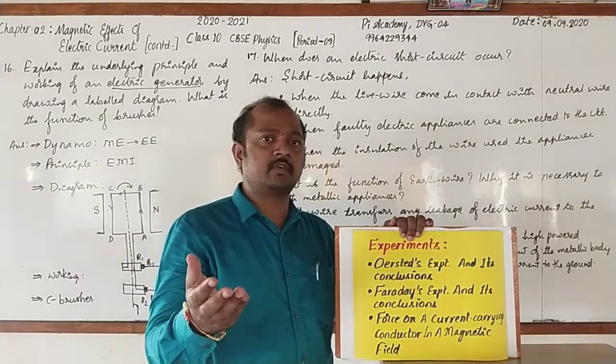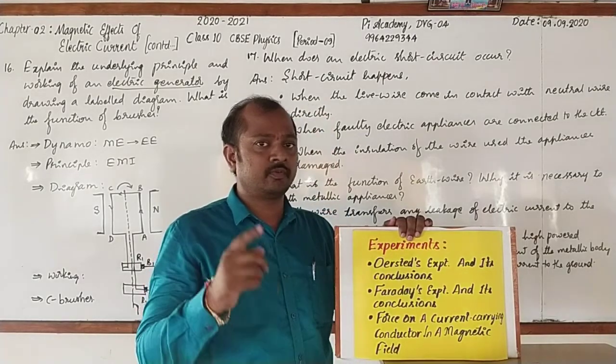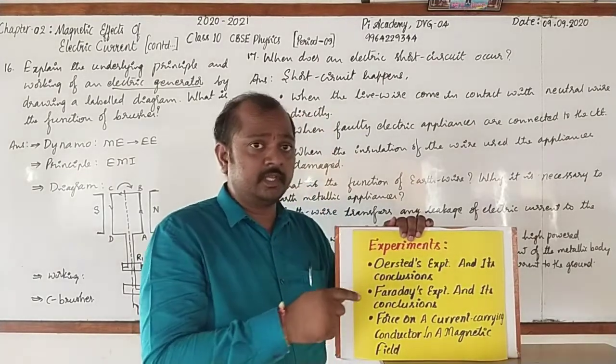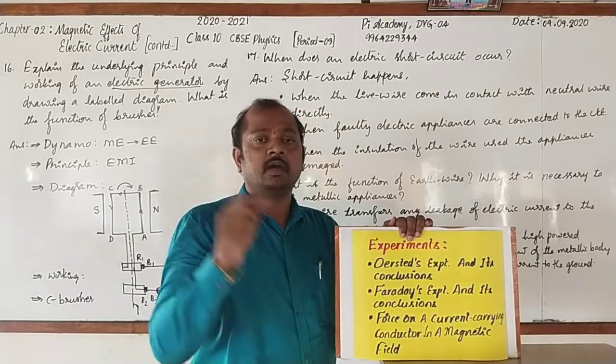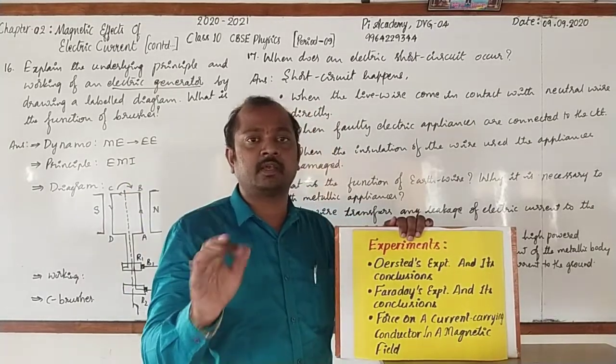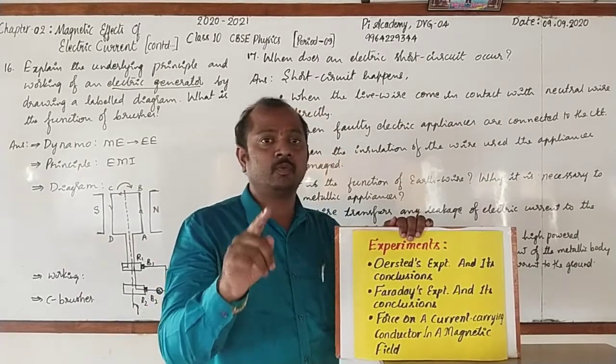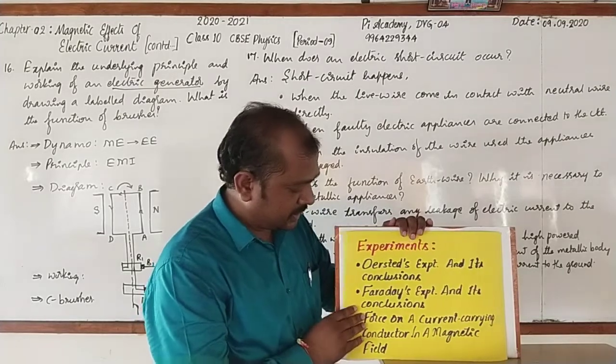The direction of this mechanical force can be known by using Fleming's left hand rule, right? And this is the principle: a conductor carrying current kept in a magnetic field experiences a mechanical force. This is the principle on which the electric motor works. Please do remember that.